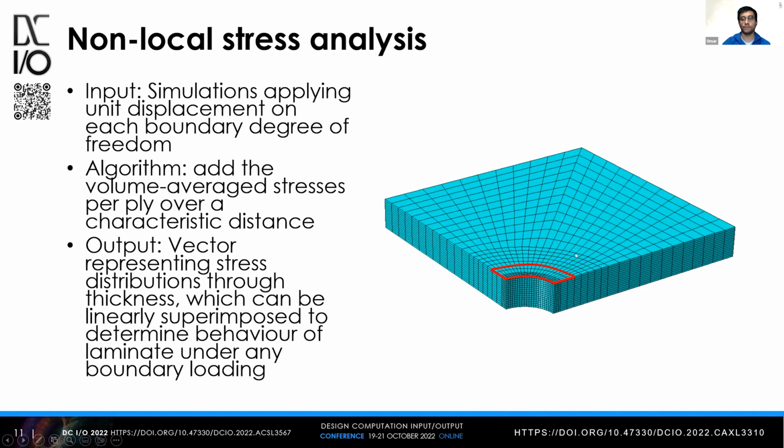Using the principle of linear superposition, the stress response in this local model, given an arbitrary boundary condition, is the same as linearly superimposing the stress responses due to the boundary conditions applied independently. So we apply these independently applied unit boundary conditions, and we monitor the stresses around the design feature, in this case, the hole.